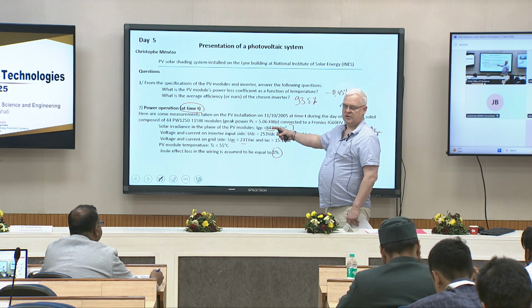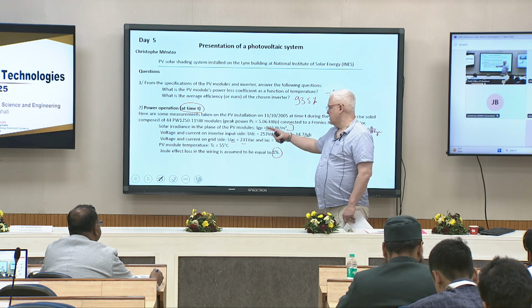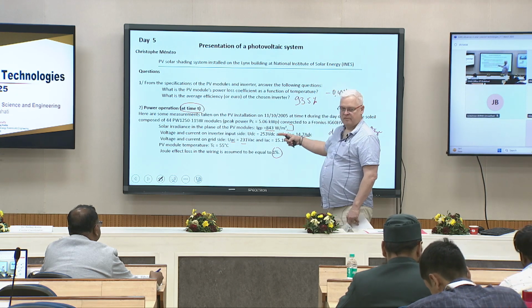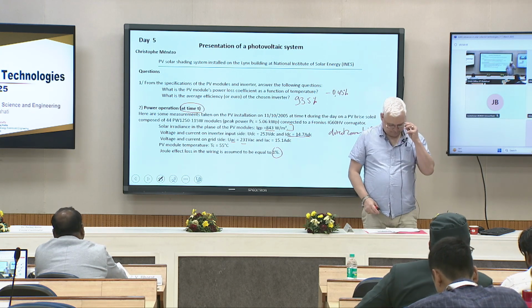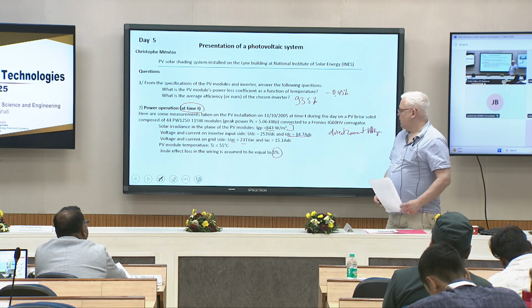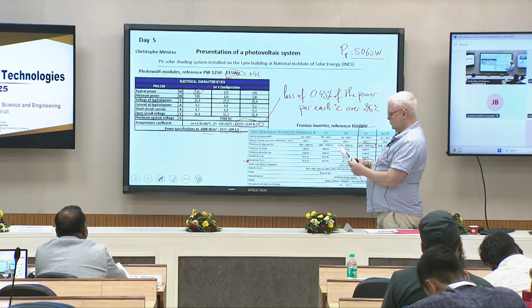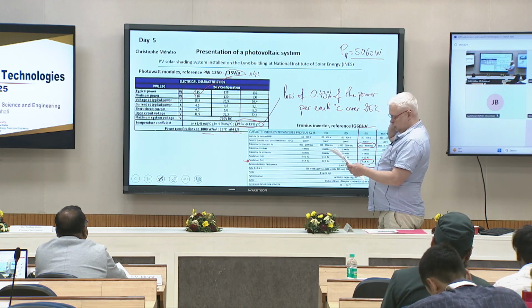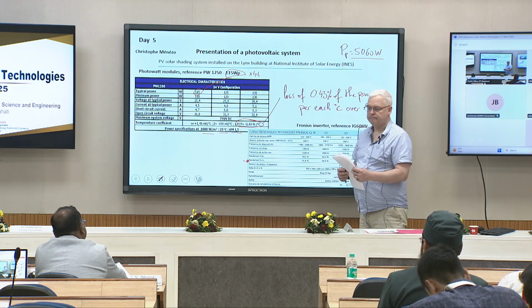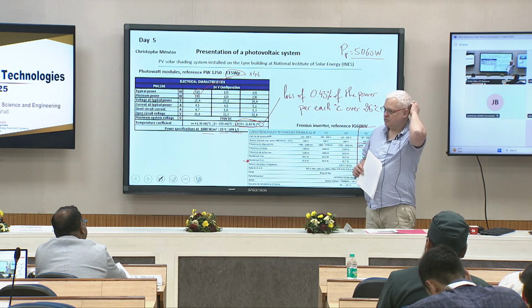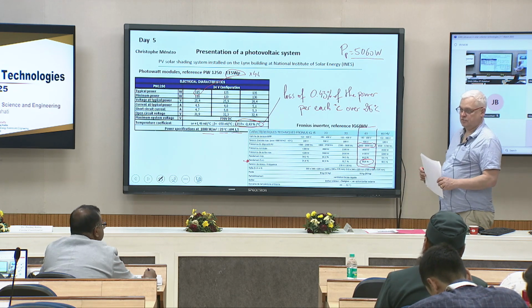We have this radiation, and this temperature of the cell is not the ambient temperature, it's the cell temperature. This is the data provided by the PV central, so it's a real value. What's the ambient temperature? I don't know if we have the ambient temperature here. It should be around 30 degrees. Maybe we can consider 25. No, we can't consider 25, because we will see that there is an effect due to the temperature, of course.